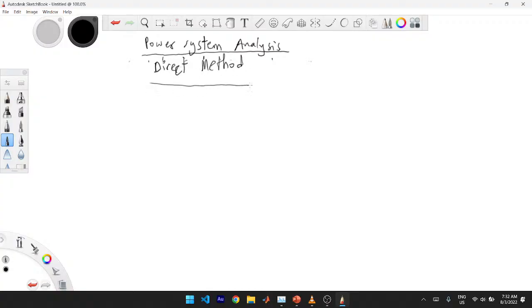All right. So first thing is to draw. If you check, first you have a generator. We said generators are represented by what? By an EMF source behind their subtransient reactance. So this is the generator, and this is the subtransient reactance of the generator, E_G double prime. Then it will have to go through a first transformer. Please be looking at the question.